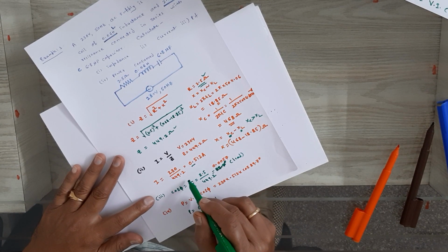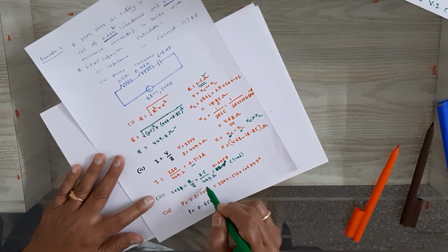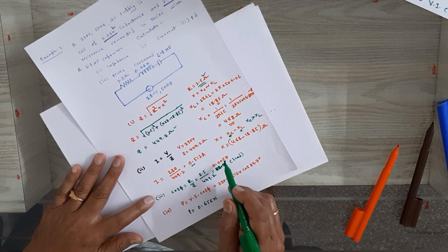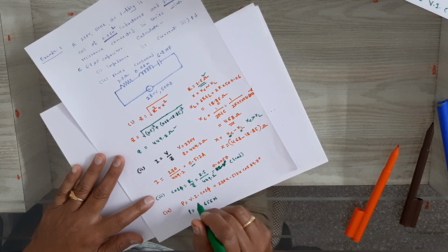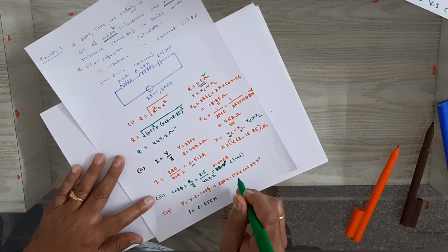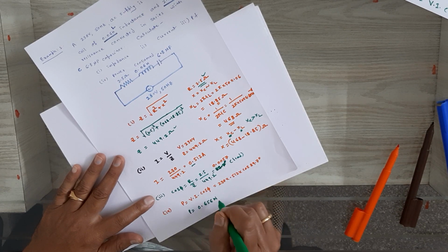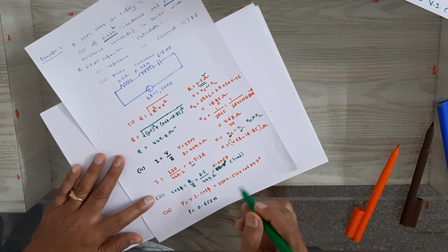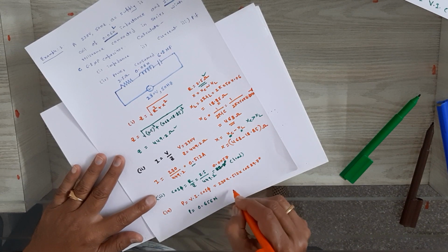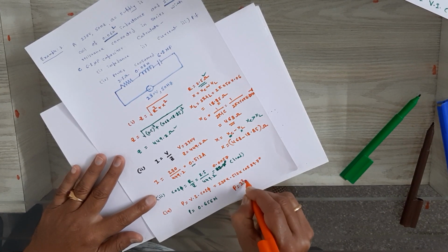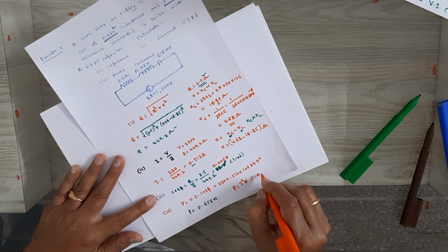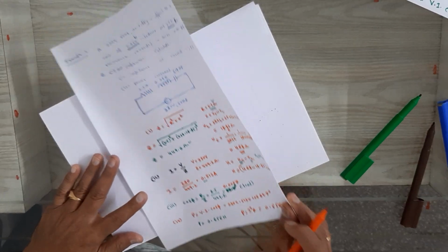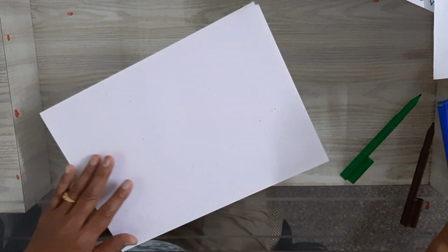Then you find out cos phi is R by Z, that is 2.5 divided by 449.2, it will come out to be 0.057. And P is equal to VI cos phi. Substitute the value of the VI and cos of 89.7, where the power consumed in the circuit is 0.656 watts. Or you can try P is equal to I square into R. Once again we are getting the same value of 0.656 watt. Okay. Now we will move to numerical number 2.